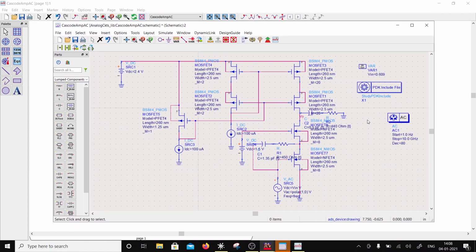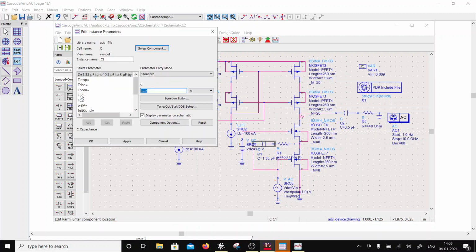Okay, so I have a compensation here. I have a compensation over here, which is around 0.5 and 440 ohms, right? So this is that compensation, and this stage will be usable up to 3 megahertz, which I don't like, but that's what I have in the first cut design.